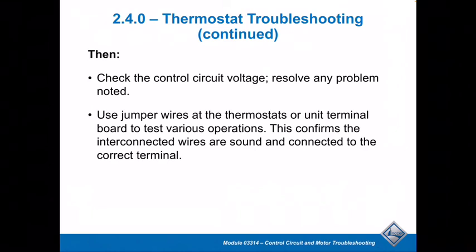Those are the things you have to do. And if all of a sudden you do that and it still doesn't work, now you better be looking more at wiring and equipment. So maybe you go to the equipment and try to jumper those terminals there. And so you can identify what's wrong or what's right.